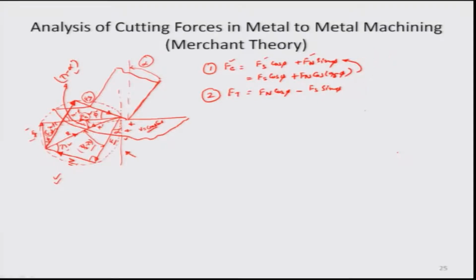Just in case of the Fc, you had seen that the component of the force Fs along the Fc is in the same direction as the component of the force Fn along the Fc. Okay. So, in some cases it may be opposing in nature, and so you have to be very careful about the signs of the force balance by the various components which would be in different directions.